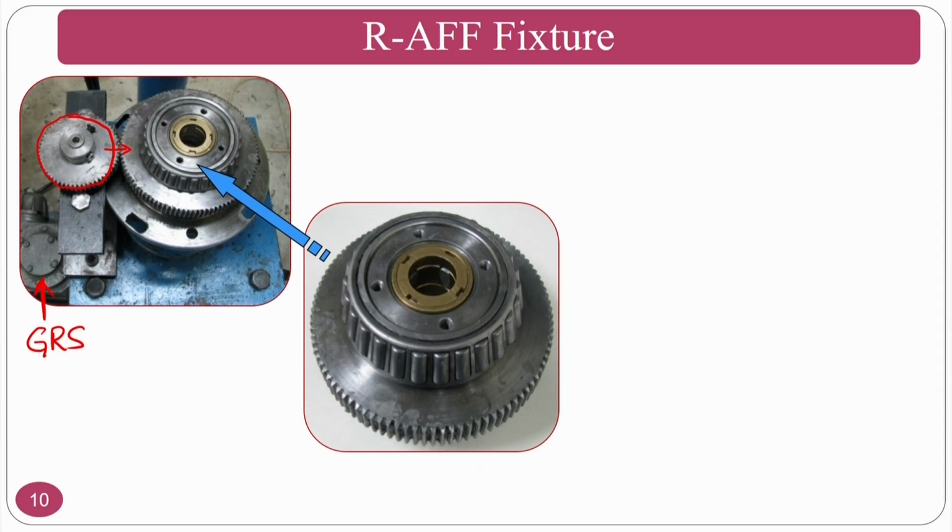Moreover, the most important thing here is that it must be leak proof, because in the previous setup everything is under static control, and only rotational motion is given to the workpiece. That is why there is a static region like the medium cylinder and pistons, which are static as far as the workpiece is concerned, but your workpiece has to be rotated. Whenever you have a workpiece to be rotated, between your static system and dynamic system you get a microns gap. In that microns gap, the basic problem is, since you are using a viscoelastic fluid,